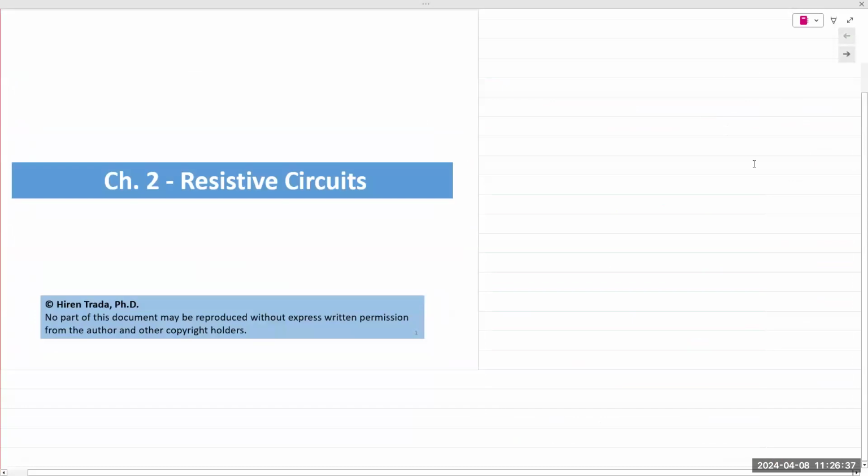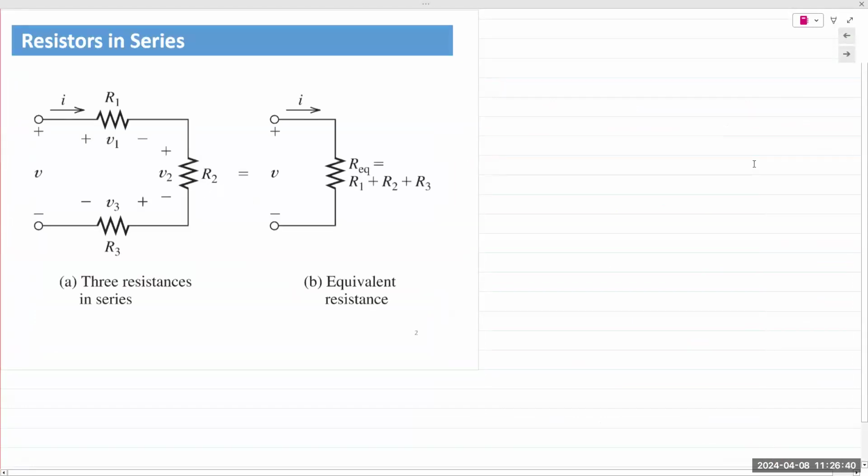All right, so as I was saying, first up is resistors connected in series. So speaking of series, how can we identify two components connected in series? Well, by looking at the nodes. A node is an electrical junction where two or more components come together. And if there are no more than two connections at that node, then those components are said to be in series. So a series connection can have no more than two connections at a single node.